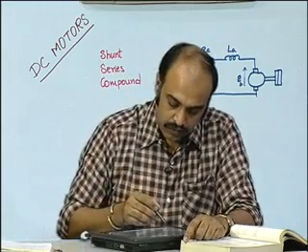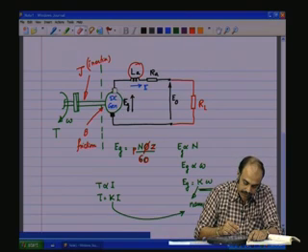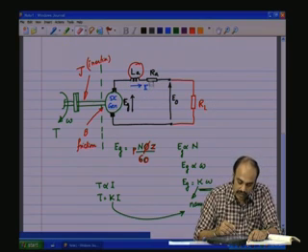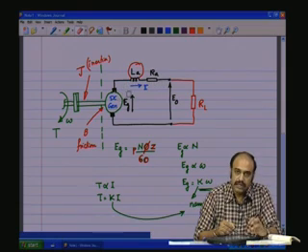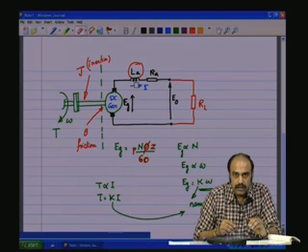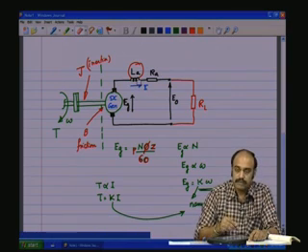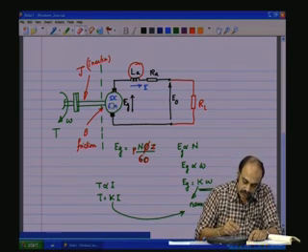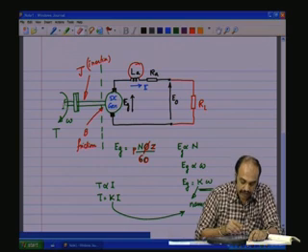drawn this figure. We have here the DC generator shown as the circle, to which the brushes are connected, and from the brushes wires are drawn to be connected to the external circuit load RL. There are two non-idealities which are brought out: RA, which represents the armature winding resistance, and LA, which is also inbuilt into the coils of the armature, the inductance of the armature coils. Now, on the mechanical side we have the shaft which is connected to the DC generator, and the shaft is coupled to a prime mover which is giving the energy.